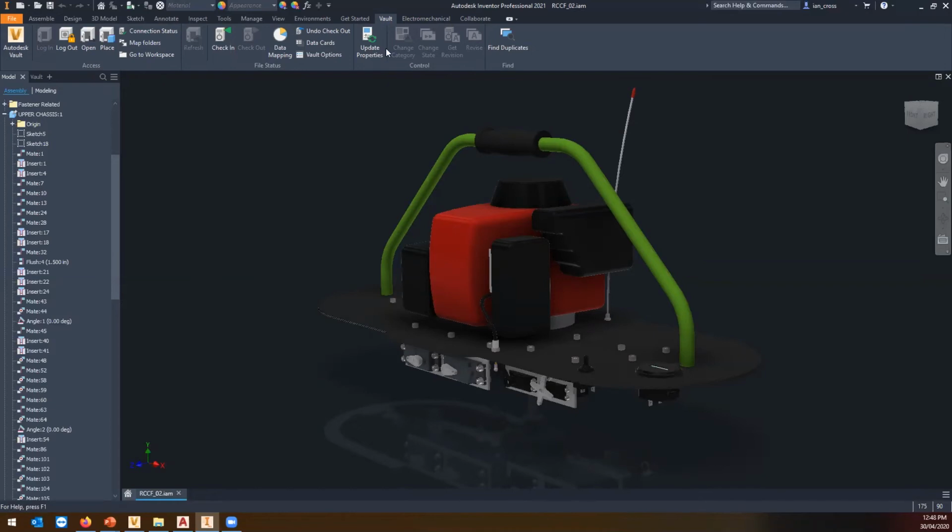The fourth option is our thin client or a web client, which allows non-CAD users who don't have a license of Vault to view released items inside of Vault. So if you've got released product, PDFs, DWFs, DWGs, IDWs, part files, whatever it may be, you can give non-CAD users access to view them read-only outside of Vault over the web. So let's have a look at the client side of things.